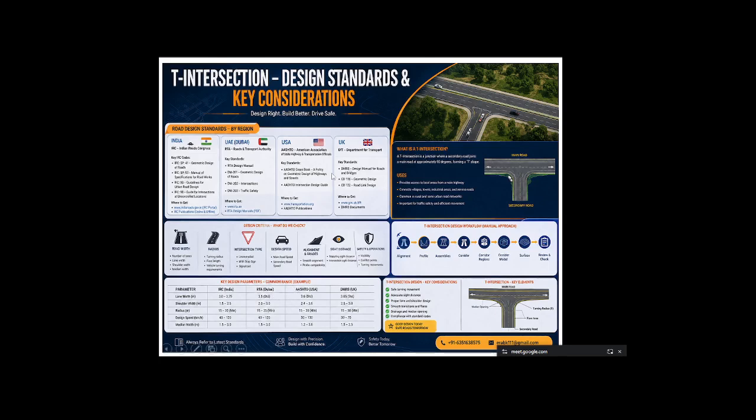Like whenever we start our road, it simply starts with the terrain condition and the design speed. So if you are working on an India project, you know which code is usable for road design or design speed or terrain condition, how to calculate the grading and all the things. You don't need to memorize it. You just need to know how to read the codes and which code you have to refer to for particular things.